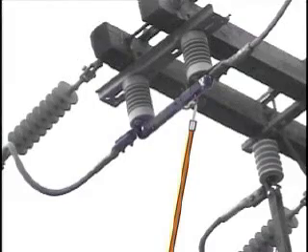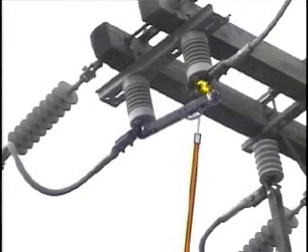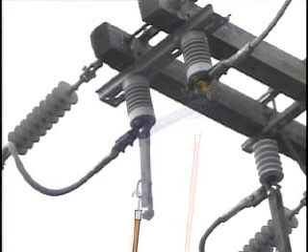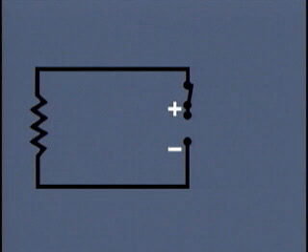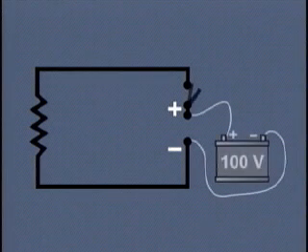However, the problem becomes really serious when we are interrupting circuits carrying several thousand amps. For this reason, on high voltage circuits, special switching devices must be installed, such as circuit breakers, interrupters, and so on. For our small lighting circuit, it will be sufficient to install a manual switch in the main circuit, and this will be opened while connecting the battery to the circuit.